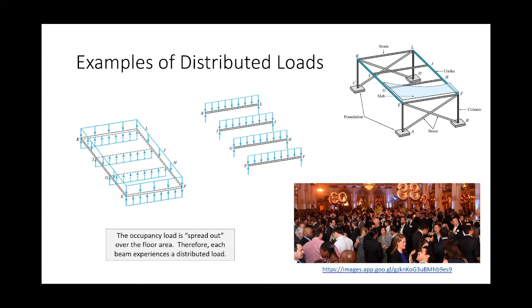What we're going to do is assume basically a pressure load over the entire floor system. And that pressure load is going to be representative of what the floor is used for. Sometimes if you ever hear me use the words dead loads or live loads, I might instead refer to live loads as occupancy loads, because the live loads represent what the structure is used for.